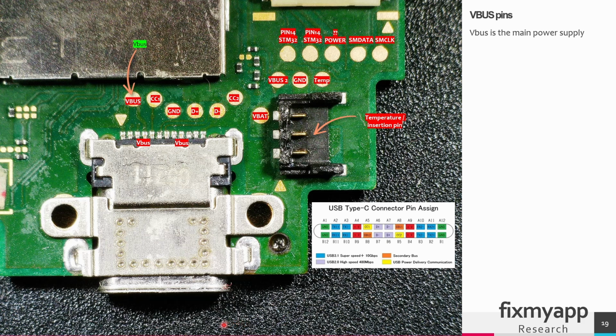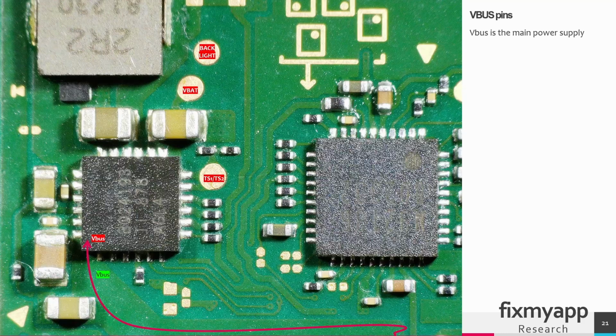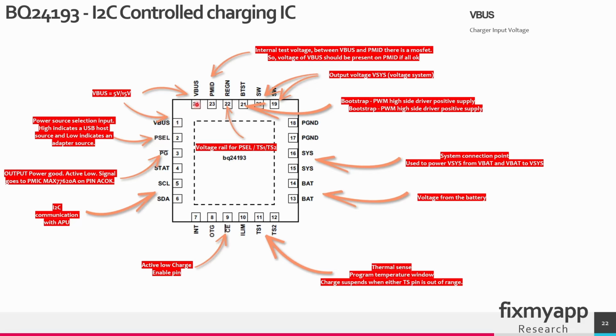So the bus voltage comes from the power supply through this receptacle to this pin, to this test point, through this fuse, through these two MOSFETs. So the V-bus will go directly into this charging IC on pin 1, and also at this pin. So these two pins are the input of the bus voltage. Pin 1 and pin 24, the bus voltage is coming in. So 5 volt, 15 volt or 9 volt, depends on what the power delivery controller negotiates.